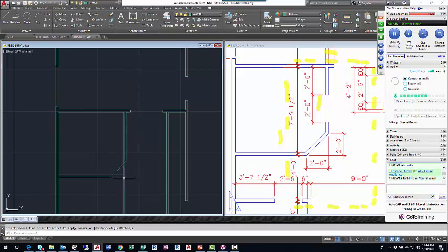And then I'll use the offset. I mentioned the best way to maintain that 3.5 inch thick wall is to offset and then trim. So I'll go offset, 3.5, enter. Left click that angled line, move up into the left. There we go. And then I'll just use the trim command and neaten up that wall intersection, make those walls hollow. Trim, enter, left click.